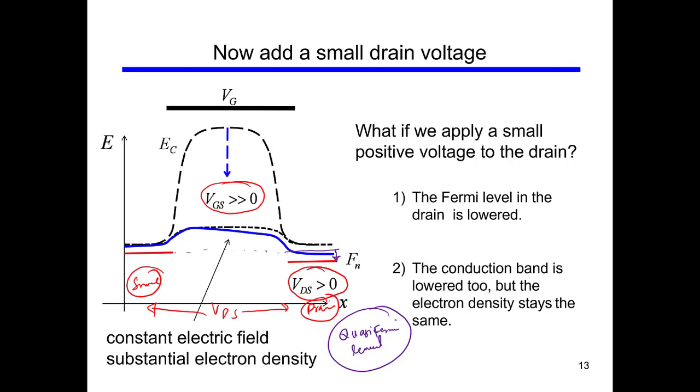You see now that the potential hill is not like this, but because of the application of drain voltage, VDS, it is something like this in the blue one. At one edge of the barrier that is near to the drain, it is lowered. It is lowered compared to the source side.